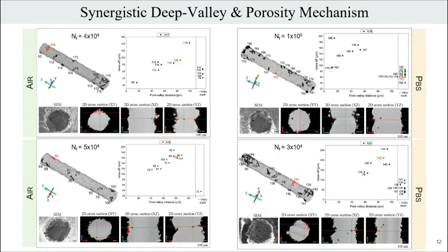However, when we go towards what we call medium to high cycle fatigue within our S-N fatigue regime, we have instead that just a valley which is among the 40% most critical valleys, so not a really deep valley, leads to the failure. This probably suggests again that there might be a change of mechanisms, due to the effect of the corrosive environment on the fatigue initiation.